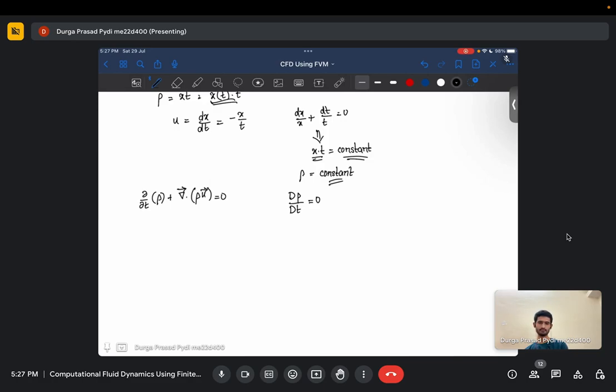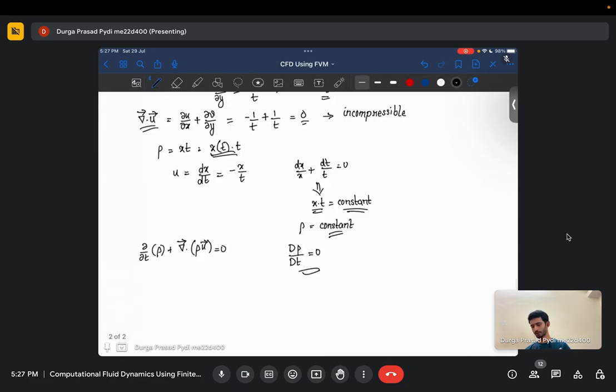Okay, I'm just thinking of this in terms of incompressibility. This isn't what conservation of mass says, right? D rho by dt is equal to... What I'm asking is, can we have a density field that is changing, which is compressible, and still have this? So you are saying del dot u can be 0 and still you can have a varying density field? That's what you are asking?